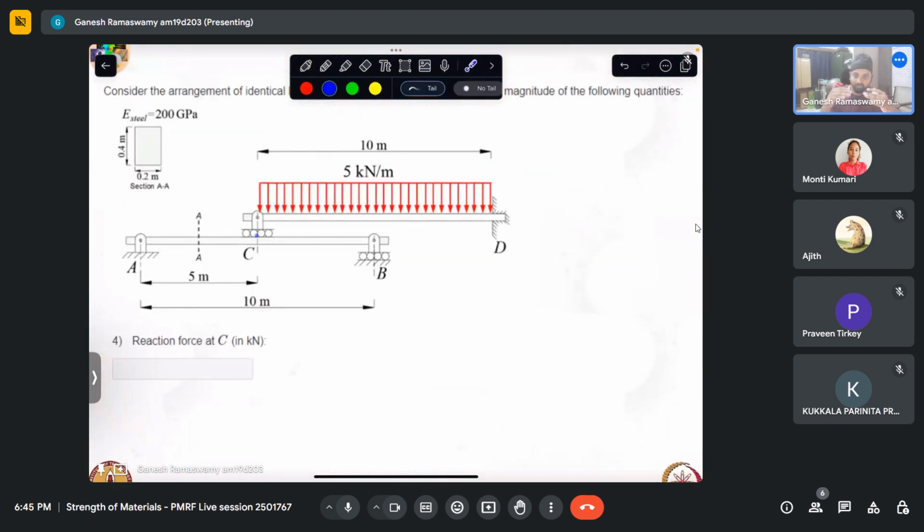Now one might ask, under the action of this roller, when it actually deforms, would it not move somewhere to the right? Which is a natural question that might occur. But since in our assumptions we are idealizing this as a small deformation problem, we will be applying everything to the initial undeformed coordinates rather than the deformed coordinates. So we will still operate with the assumption that the roller is exactly at the center, C, although this does not create a lot of error. So that is why we proceed with this.